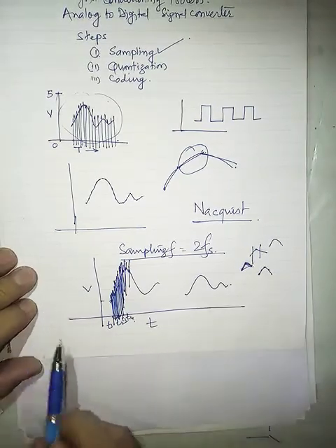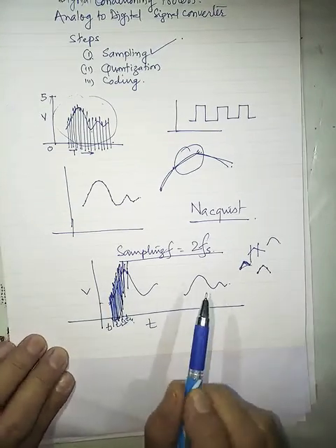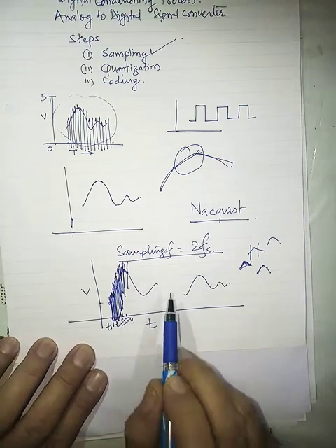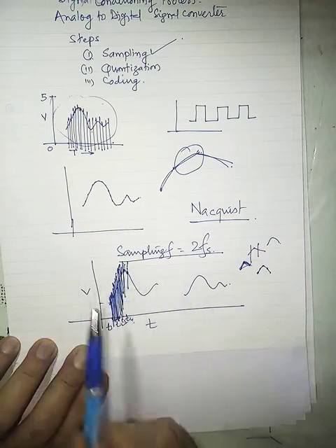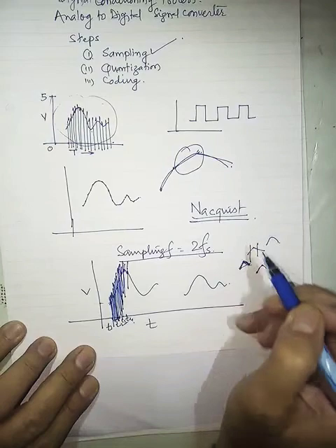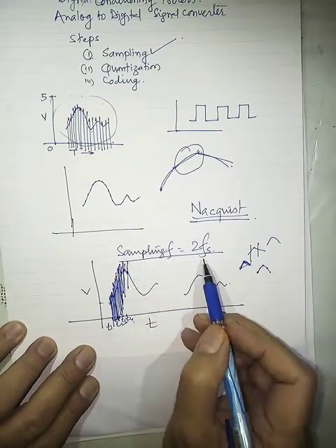This process is known as sampling, and in sampling, the frequency should be as high as possible to get the original results or results near the original. Nyquist's theorem is a sampling theorem which says the sampling frequency should be double the frequency of the varying signal.